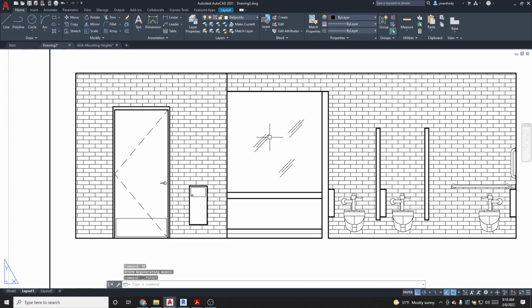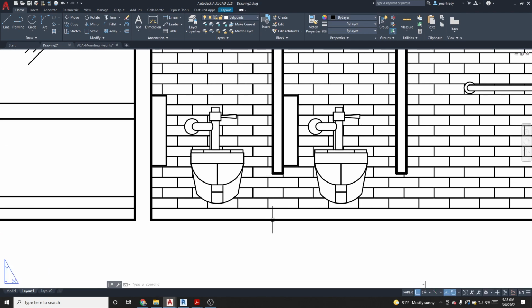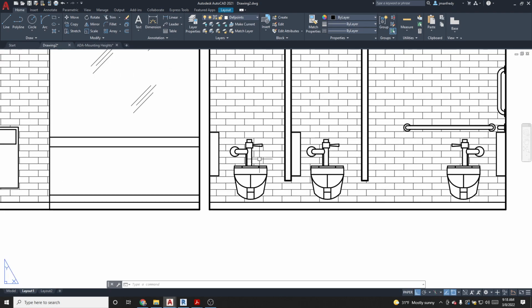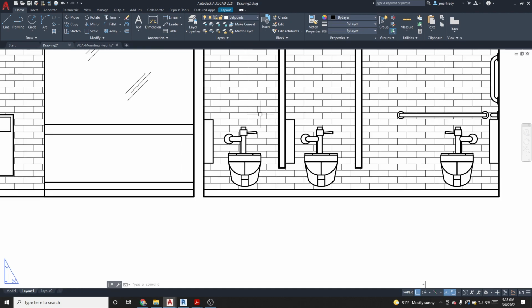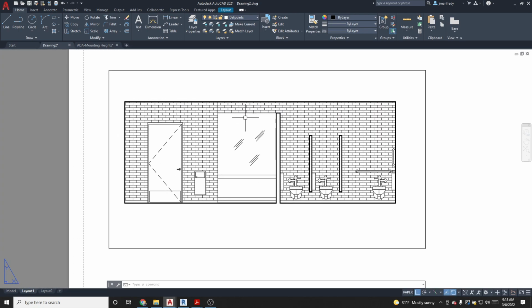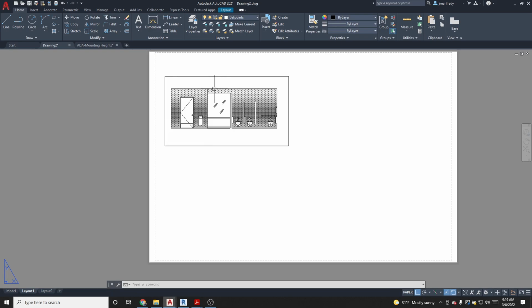So now this drawing is accurate. This is what your drawing should look like. These are the line weights. Detail bold is the heaviest on the outside. Detail medium is not as heavy as detail bold. And then in the background are detail fine. And the thinnest line here is the hatch pattern in the background there. You see that's a very thin line back there. And so these drawings look three-dimensional, although they're all two-dimensional drafting. That's the M view for that one elevation there.